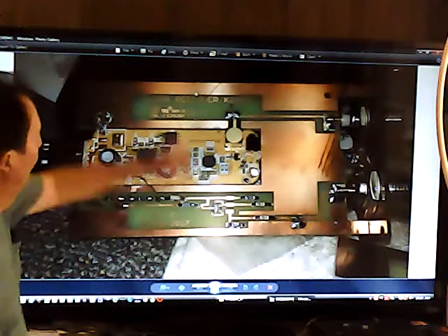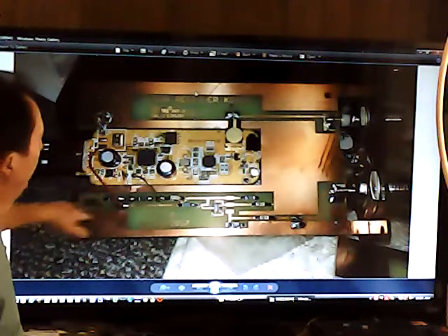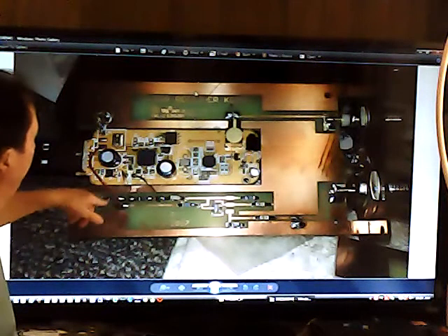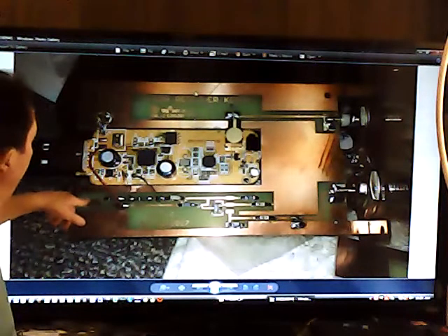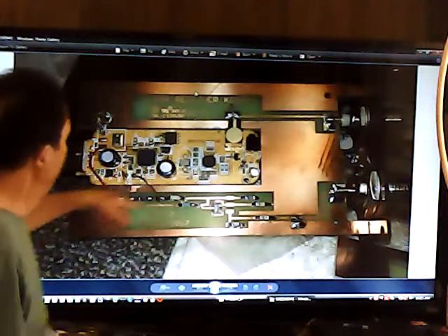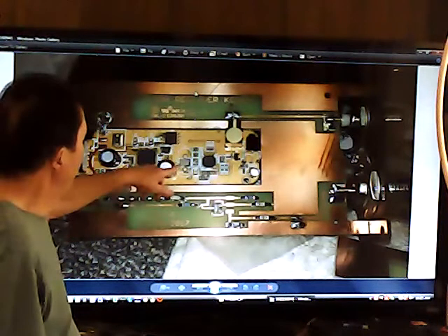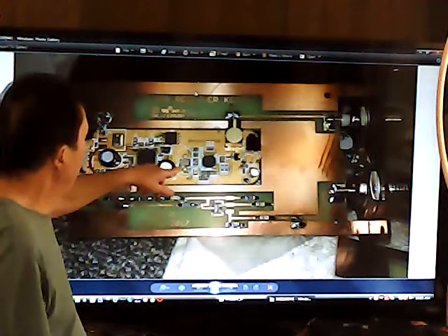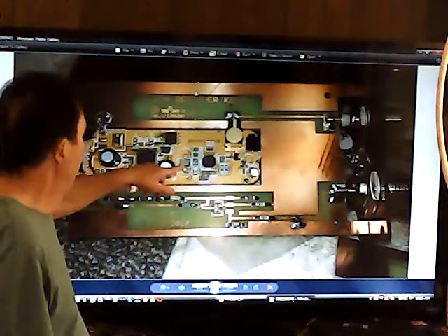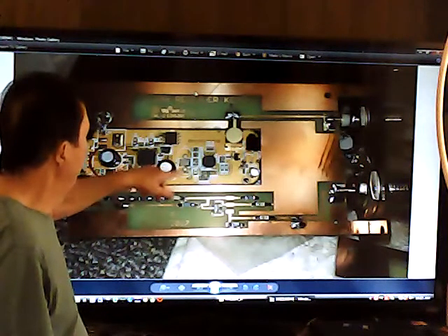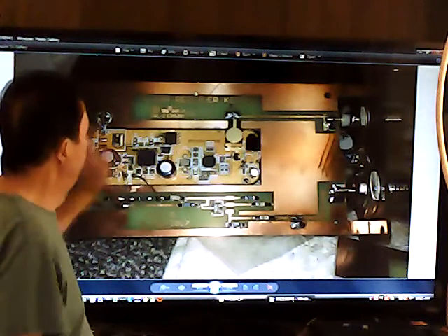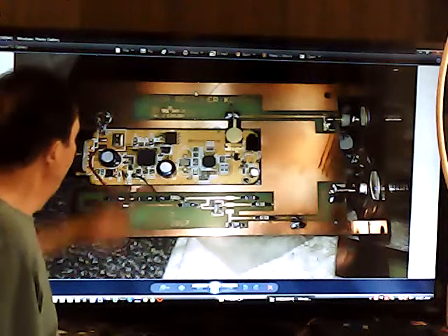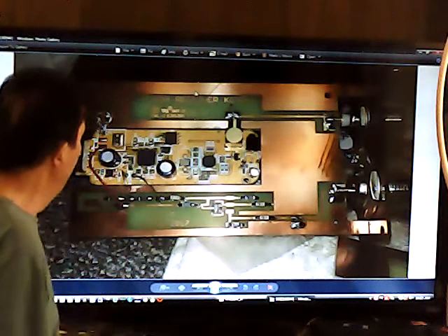This is the motherboard and the RTL device that I have in my RTL SDR unit. In this particular application, I've selected a TV dongle that uses a temperature controlled crystal oscillator, and it's always dead on frequency. You don't have to worry about any frequency correction.